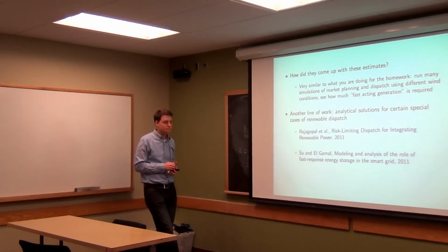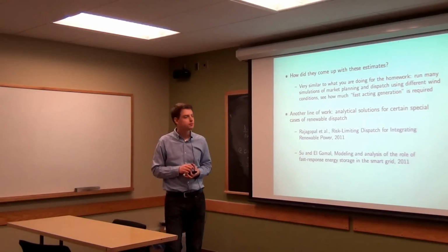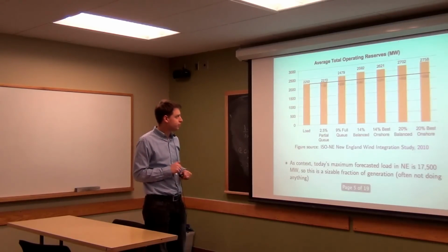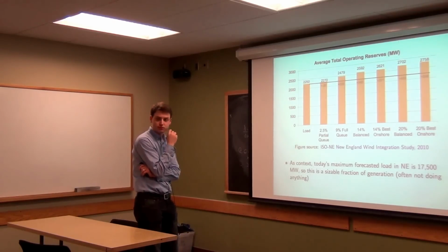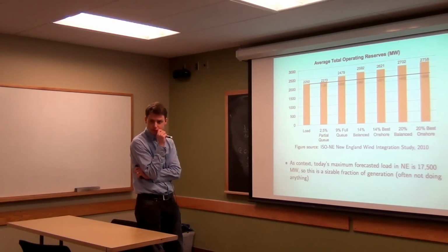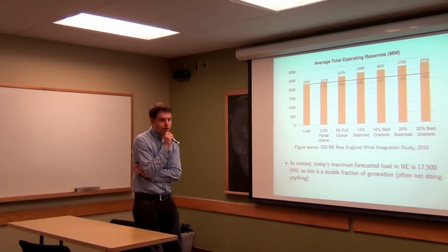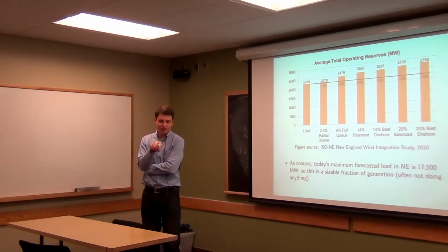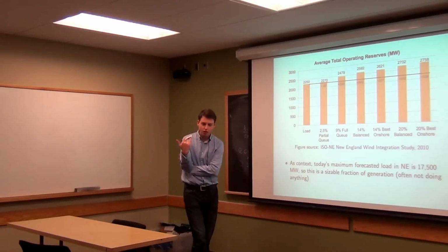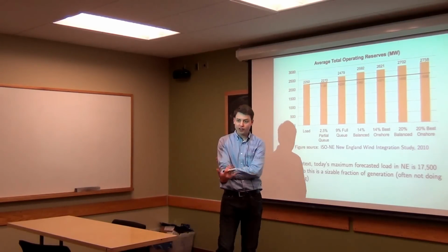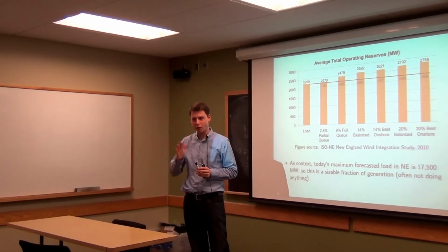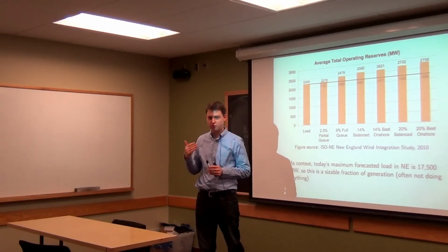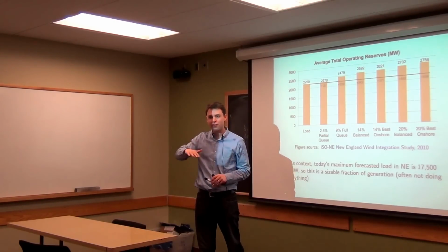Yeah. Seems a little off for the reserves, or the ones before. Yep, these ones. So as more wind comes on, won't you just take a fixed percentage, where you'll have to add this amount of reserve just to keep it from failing? So it can actually be complex, because what it depends on also is how correlated the wind is with other wind farms, right? If all wind came on or went off, then yes, you would need a fixed percentage, if wind was either full on or full off.